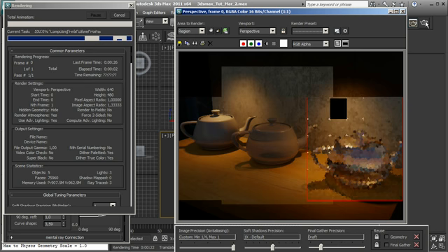Let's wait, and you'll see that we have more reflection over the glass. And you see also that we have more specularity over the surface, and the shadows now are more visible because we have also the shadows due to the reflection. And that's another way to simulate some different glass properties.